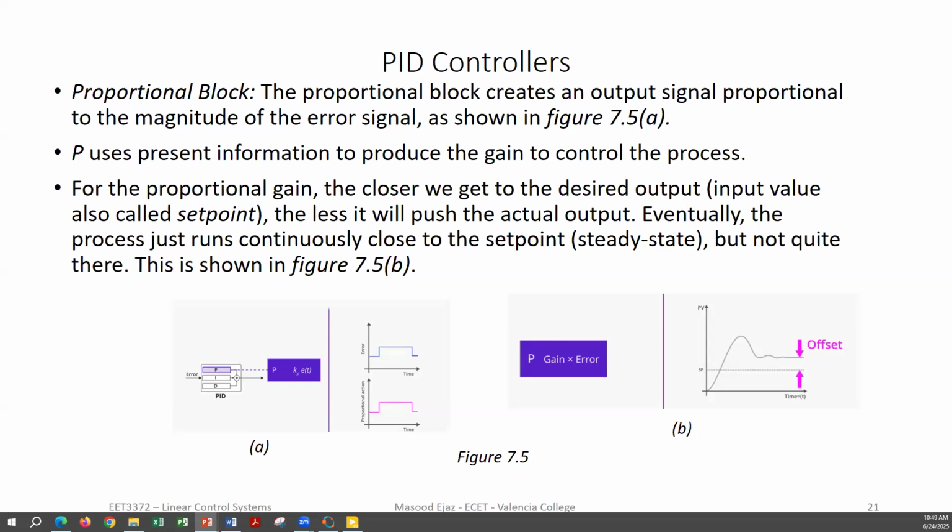In the time domain, after it settles down, you will have your steady state value and your output, and they will have some offset or some error between the two of them with the proportional path. And that error depends upon how much gain you are supplying for the proportional path.